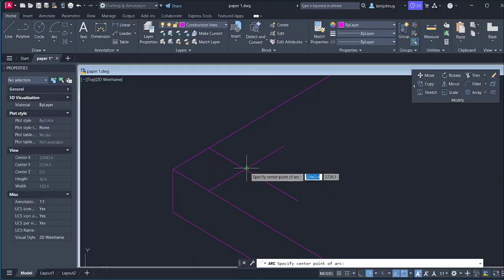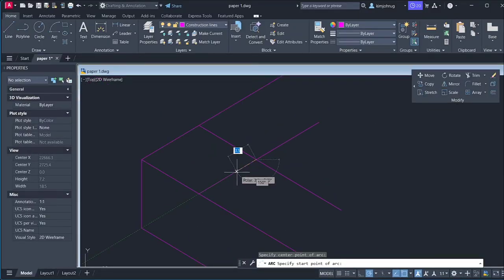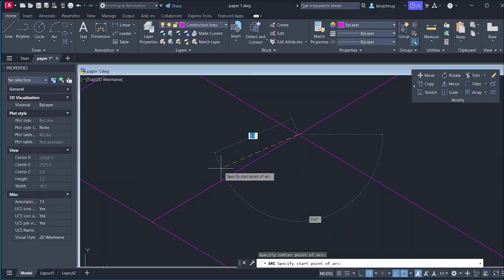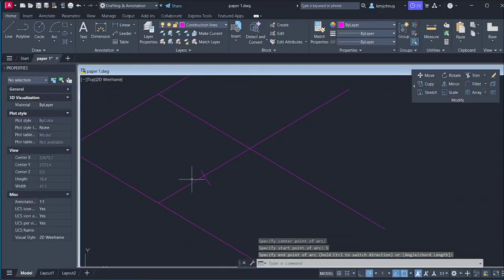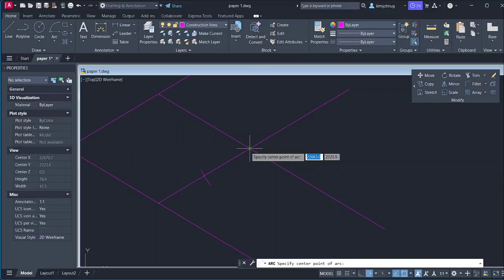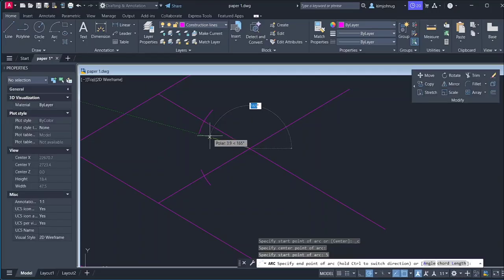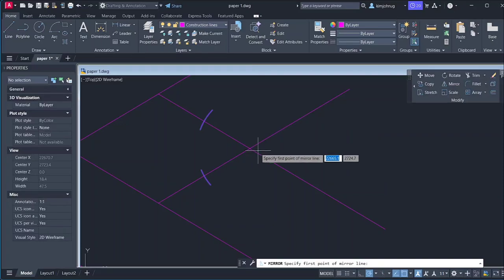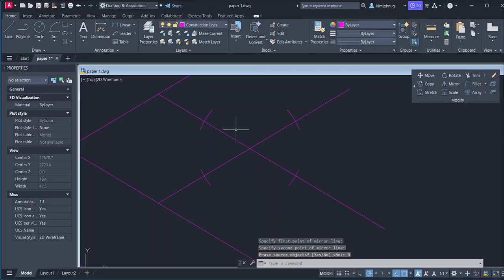Right? So if I select this and I stand here on my center, I want to draw an arc of radius 5. So after standing there, it tells me specify the start point or by placing a radius. So I press 5, and I draw an arc. You see this? So I also want this side, press 5, then draw another. So if I want, I can just mirror these two, facing on this, right? 270. Don't erase, so that I have those.